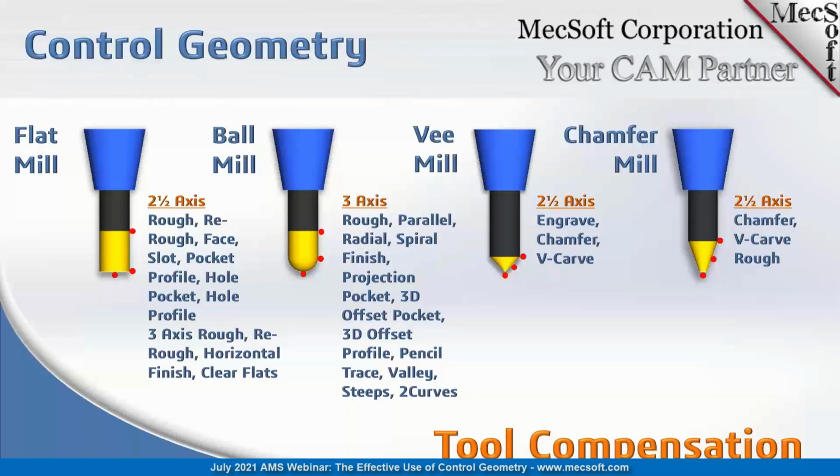In engraving, the tip of the tool follows your control geometry exactly. You can even go so far, and we've got an example of this as well, as to draw your toolpath curves and use engraving to make your tool follow that path exactly, and it won't deviate from that path. So if you want precise control over your tool, you can use the engraving operation, and you can use any tool with it, and the tip of the tool will follow the engraved toolpath.